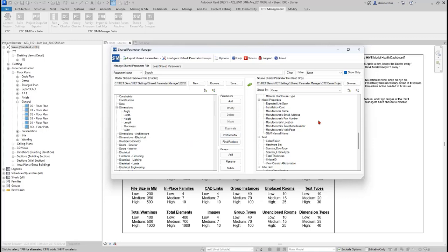Well, now what we can do is either start comparing them against the master, or start a brand new file, get the groups added the way you want them and based off what you need, and start loading up those other shared parameter files and bringing what you need across until you've gotten through them all, and now you have one singular shared parameter file to distribute to the office. And then if changes are made to the parameter definitions or the parameter types, then you can use family processors to go ahead and update your content to utilize the new parameters.